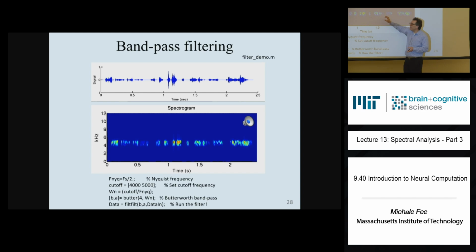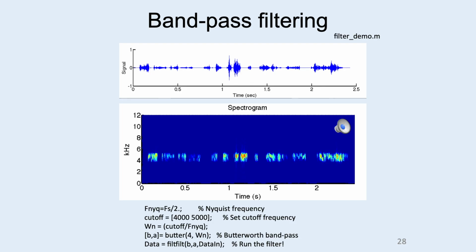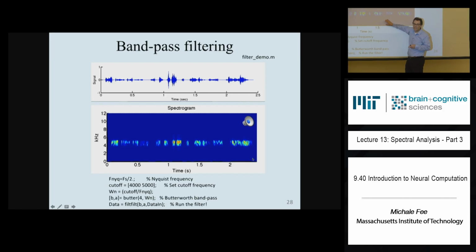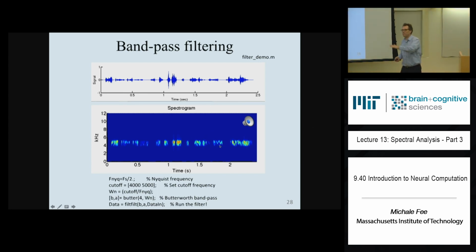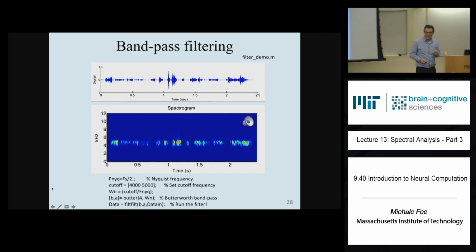So then you would run a bandpass filter right over a 2 kilohertz band, and now you'd get a big signal whenever that formant passed through that band. Okay? And then you would send that to an amplifier and play a noise burst into the person's ear. All right. We do things like that with birds to find out if they can learn to shift the pitch of their song in response to errors. Okay, so yes, they can.